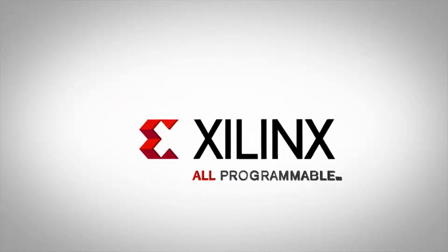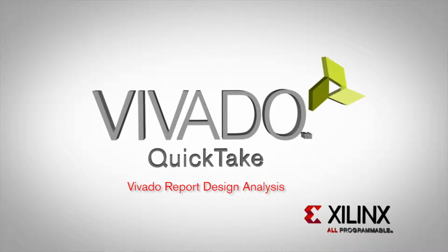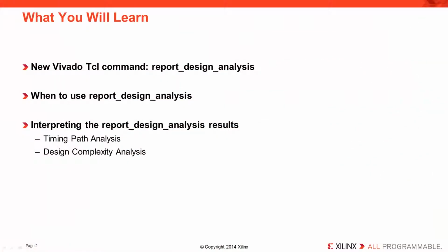Hello and welcome to this Vivado quick take on the Design Analysis Report, an important new tool in the toolbox of timing closure techniques. In this quick take, you will learn about a new Vivado Tcl command called report_design_analysis. It provides key design information that is typically gathered by timing closure experts. You will also learn where this command fits in the design flow, when it is used, and most importantly, you will learn about the different modes of analysis, timing and complexity.